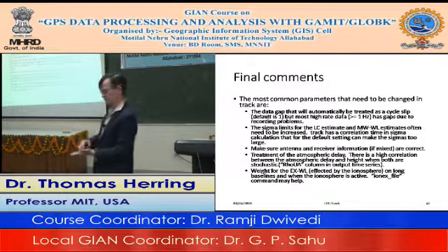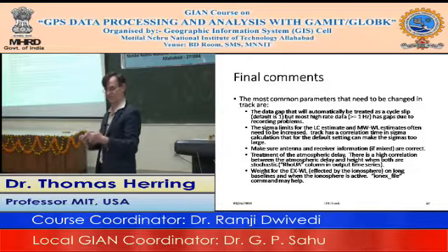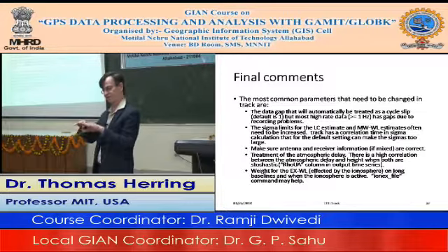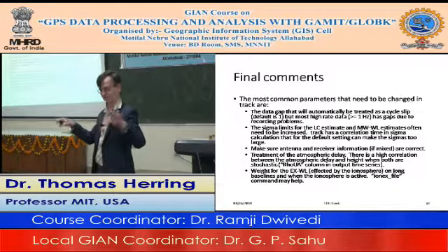One of the issues is there's always extremely high correlation between the atmospheric delay estimate and the height. And so often we end up running atmospheric delays as just constant parameters to stop that happening.